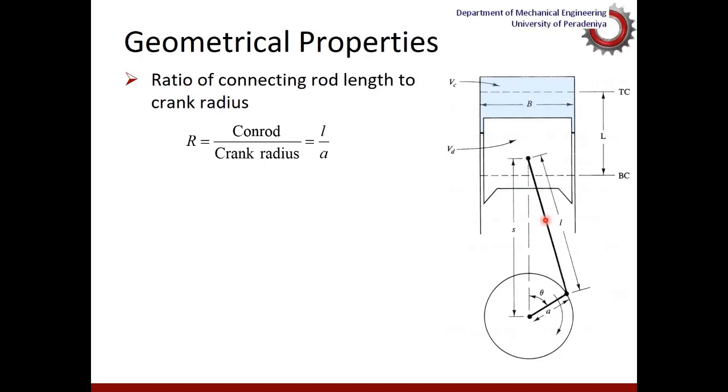So minimum heat losses. And at the same time, when it comes to friction losses, most of the friction comes due to rubbing action between the piston rings and the cylinder wall, and also there will be certain movement of the piston. The piston also turns this way, and there will be some rubbing taking place over here, this part of the piston, as well as the cylinder walls.